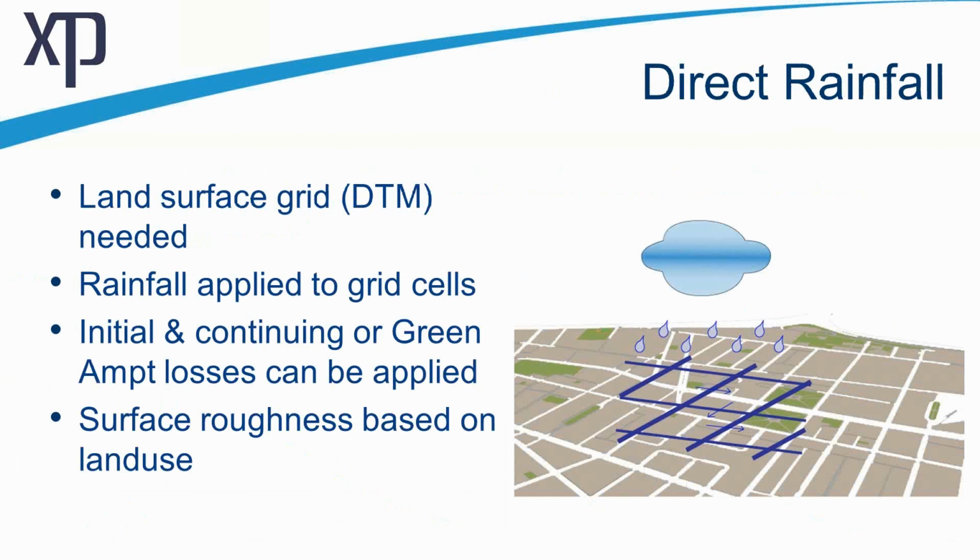And just before we wrap up, the latest, I suppose, advancement to hydrology that is now available to the engineering fraternity is direct rainfall or 2D rainfall. And it is being seen as a simplified method. In part, I will say that it is taking the engineer away from hydrology at times, where the most difficult thing to define is the first point that David discussed earlier, which is the identification of those major interfluves, those major catchment boundaries.